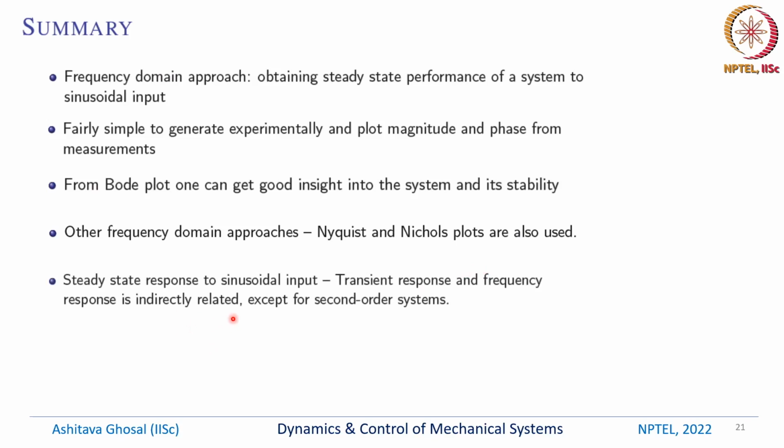The steady state response to sinusoidal input is basically what we get. It is not really related to the transient response, and frequency response is only indirectly related to the transient response. So except for second order systems, we cannot say much about the transient response of a system from the Bode plot.